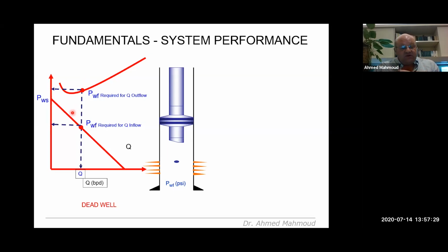The reservoir producing potential does justify the investment, and yes, a lot of operators and oil companies will put the investment to move the inflow to intersect outflow. Now, if you are in marginal fields that are economically not justifiable, you cannot really justify the big investment of shifting the inflow curve by applying water injection or gas injection, then your next option would be to try to move the outflow curve to move and intersect your inflow.